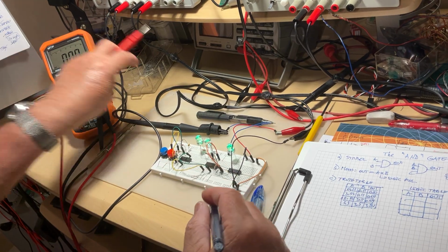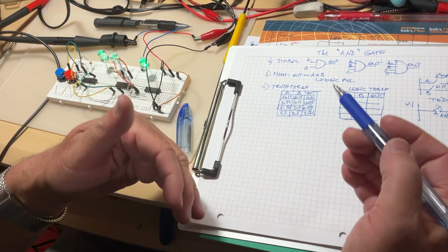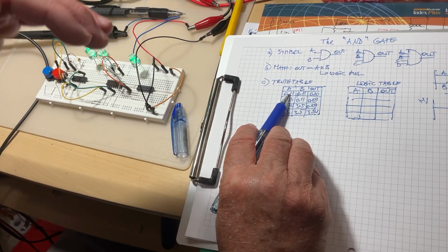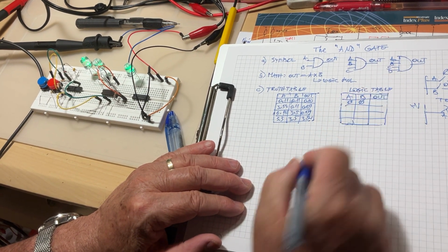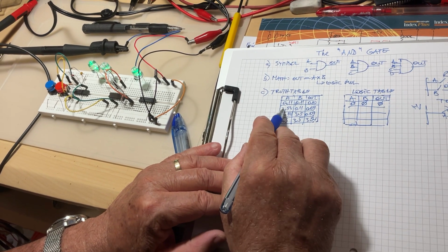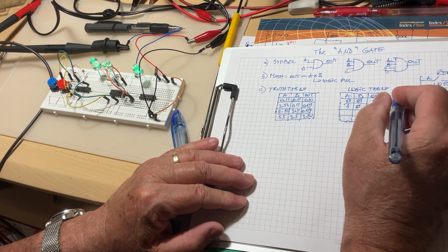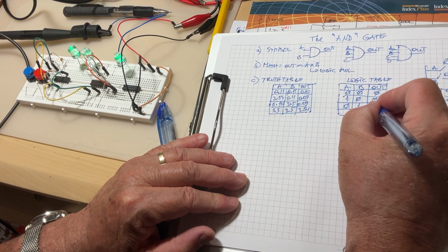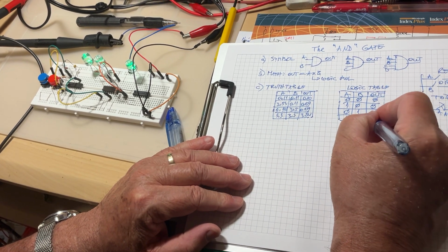Now we don't need a multimeter anymore. We convert this table into the logic one with zeros and ones, the binary. Remember, for the inputs, when they are lower than 0.8 volts, they are zero logic. So the first position, zero logic both, and the output is zero. Second situation, this is 1, this is 0. The output is still 0. Third situation, 0 logic, 1 logic. The output is still 0. And the last line here, 1 logic, 1 logic, 1 logic.